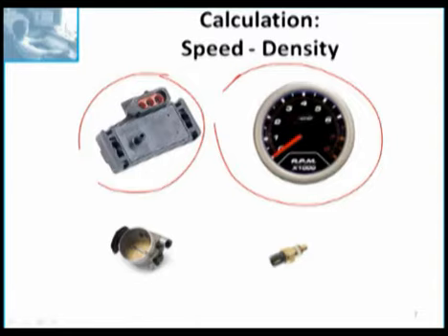And it needs to be comparable to the baro that you have seen on good running cars at your location. The weather station baro is not how you want to compare a MAP, because the weather station baro is corrected for elevation. And so at my house at 3,000 feet, a car would show me a baro of 27 inches, but the weather station on a sunny day would say I had 30 inches of barometric pressure. It's a different thing. So you want to look at some good cars, see what the baro reading is, and that becomes your number.